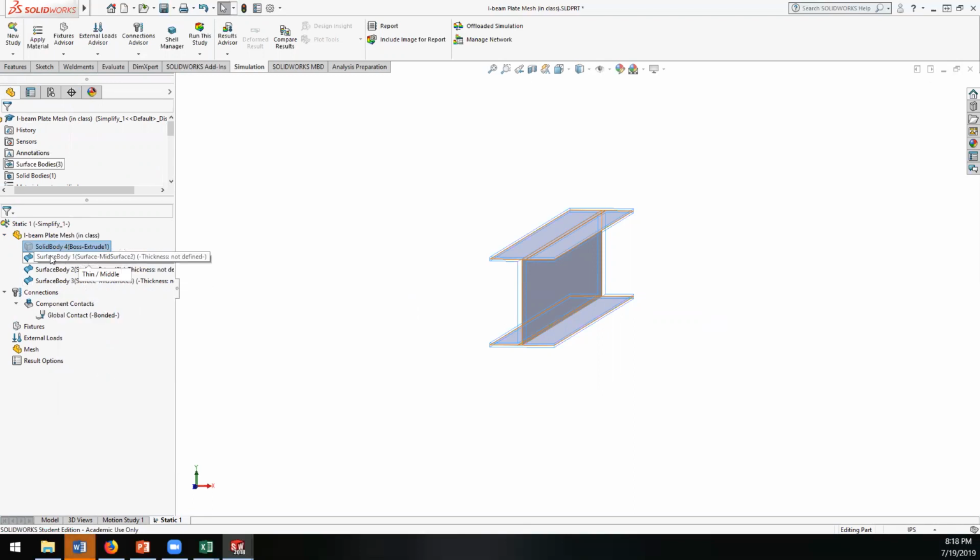And now look, this says that it's a solid body. And this is telling you it's a shell. It's only a plane. So these pictures there mean it's a shell mesh. In fact, you could right click this and say shell manager and actually make the solid body a shell. So you didn't have to necessarily go do this. You could do the mid surfaces in this part of it, but it's a little harder to control, I think, because you have to extend surfaces and all that. I like to do it in the CAD.